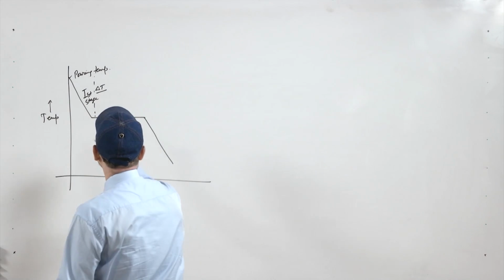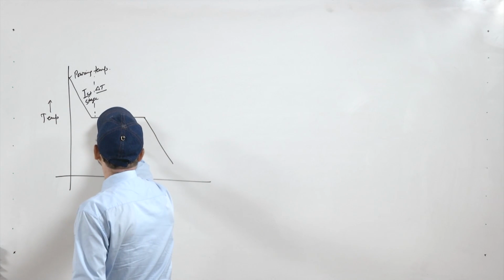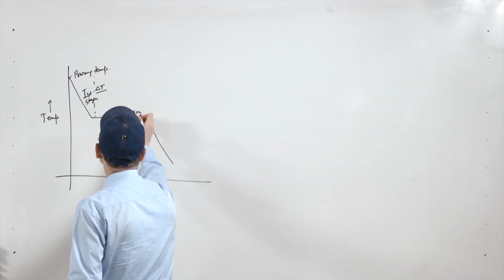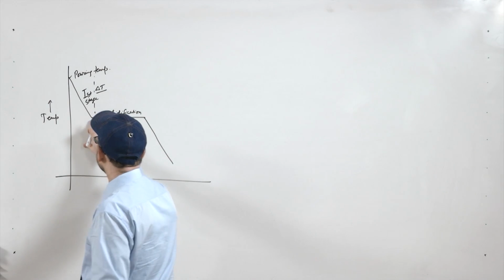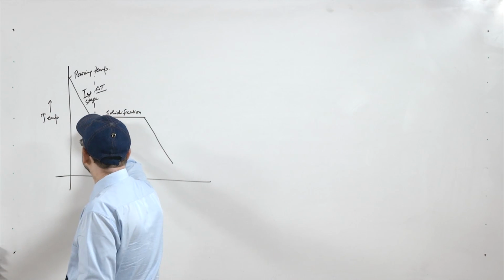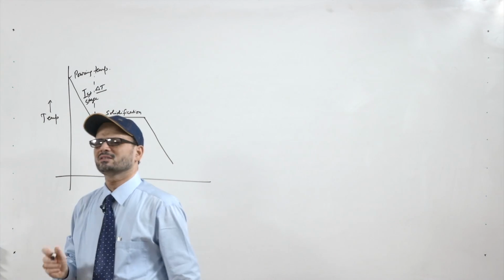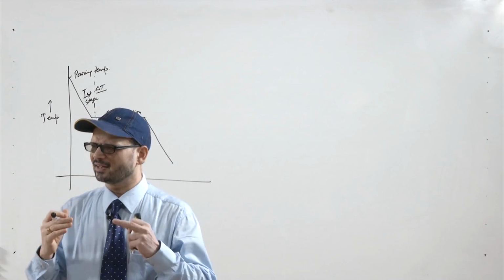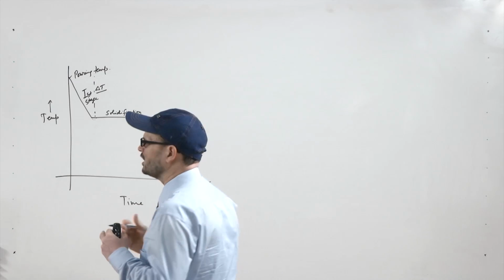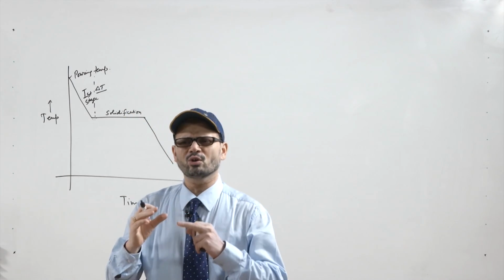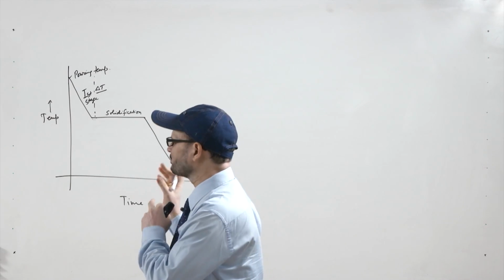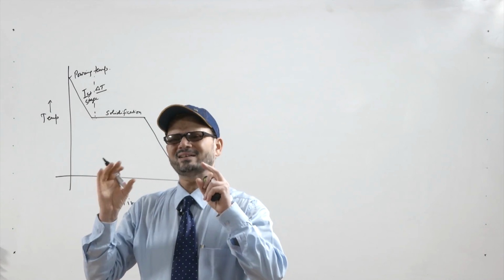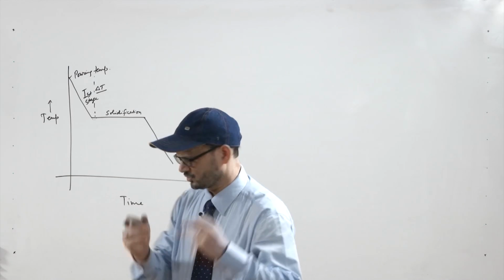Similarly, this is the second stage contraction, this is the process of solidification. So, during this process, as we have already understood, when the metal reaches this temperature with a small degree of undercooling, the onset of nucleation is there, and then with the mechanism of nucleation and growth, the solidification starts at certain points, and that will be governed by the conditions of free energy and others.